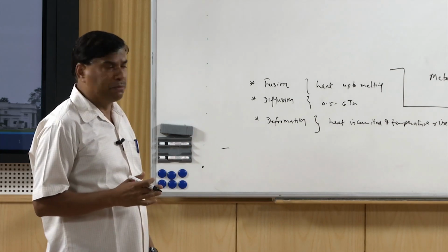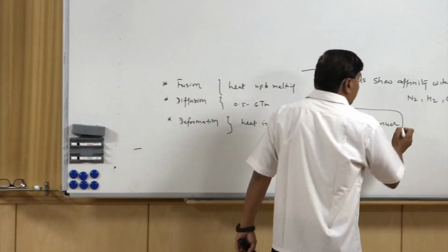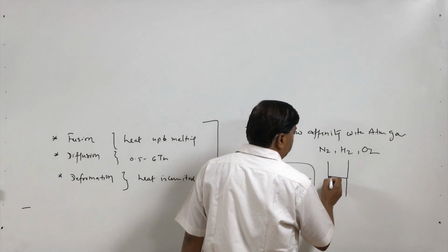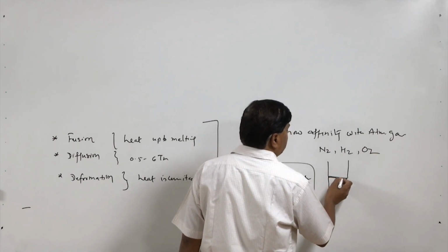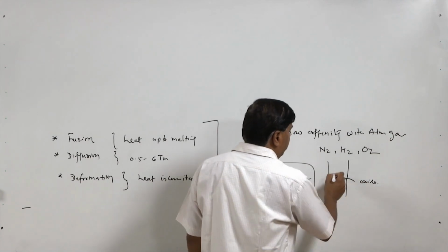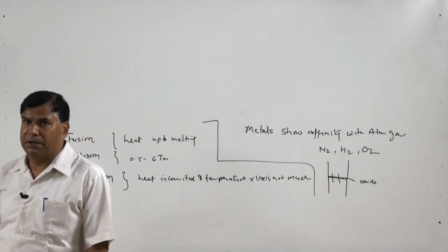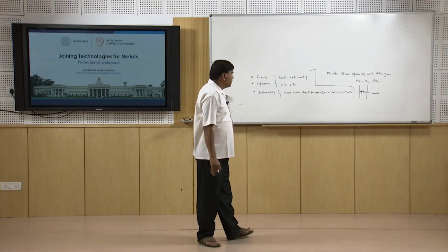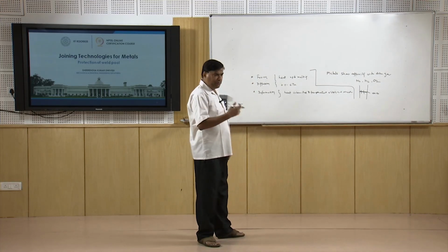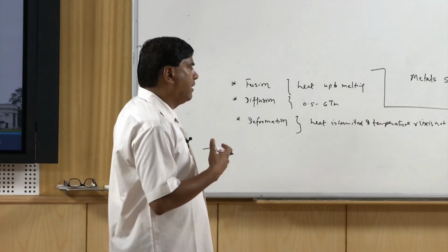of the components to be joined, because of the formation of any layer at the interacting surfaces. Say in case of diffusion, if any layer of the oxides or nitrides is formed, then it will hinder the diffusion across the interface and will act as a barrier for the development of the joint. So, it is not good, we need to protect the joining process by diffusion using either inert gases or vacuum.